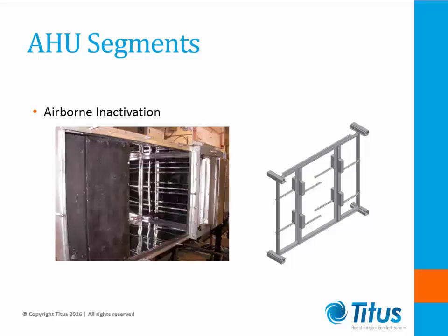Using this option, a reduction in airborne organisms can be rapidly achieved. Air entering the air handler is subjected to radiation at the time of entry. The airflow can be disinfected up to 99.99%, depending on the number of lamps installed, length of time of exposure, and the dimensions of the air duct.